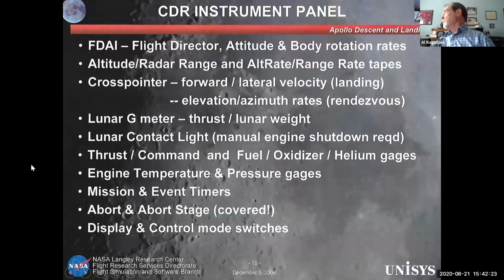The commander's instrument panel had a flight director. The attitude and body rotation rates were all on that FDAI. It had your roll, pitch, and yaw, and your body rotation rates, and what the flight director was telling you, what the computers were saying you should be doing.